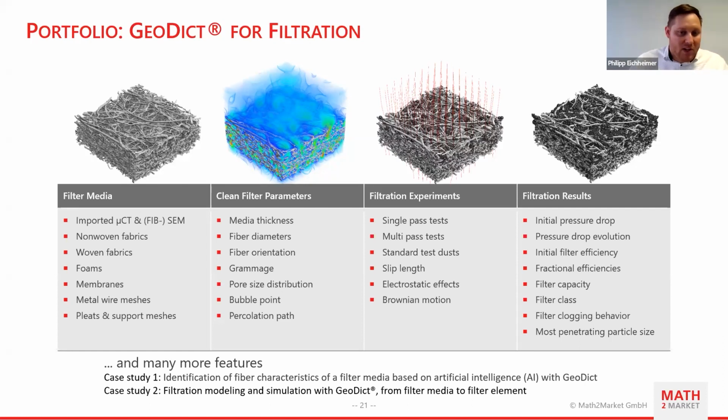And then in the filtration simulation, of course, we're interested in filtration-relevant parameters, which in our case are the initial pressure drop, evolution over time when we have filter lifetime simulations, filter efficiencies, and capacities. We can have filter classes tested. And what is also very interesting is most penetrating particle sizes. Besides that, most of the parameters can be accessed with our Python API. So if you have the need for individual analysis, there are nearly no limitations. Many more features are on that.